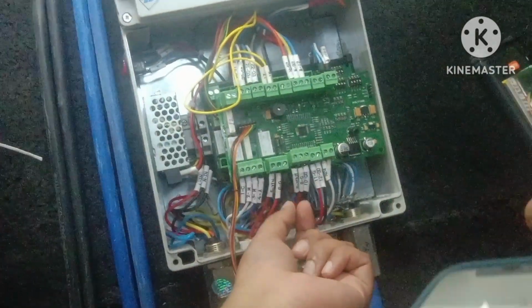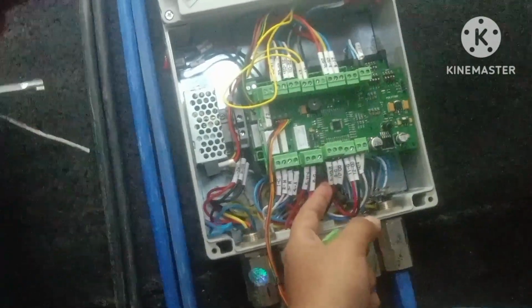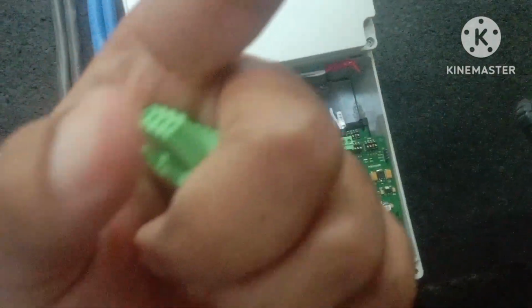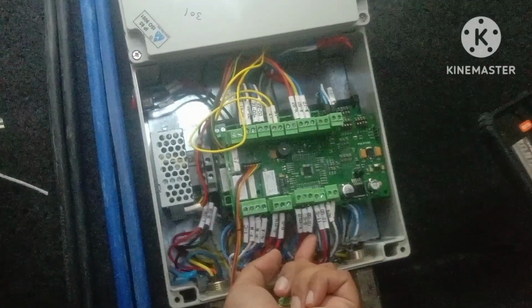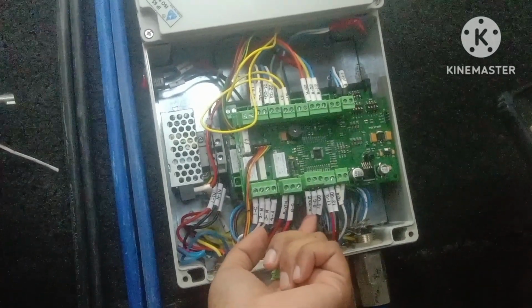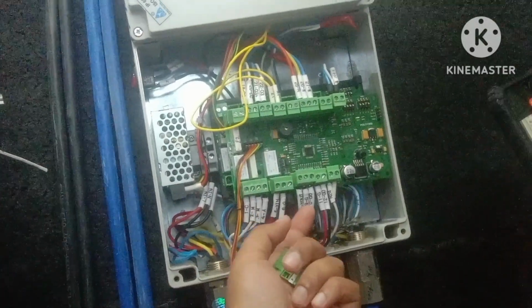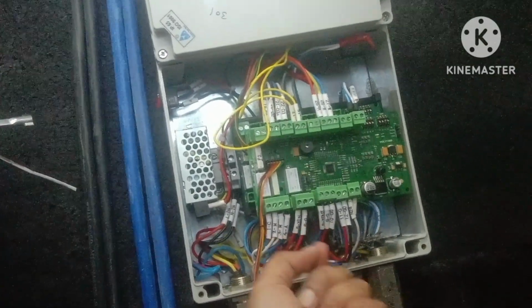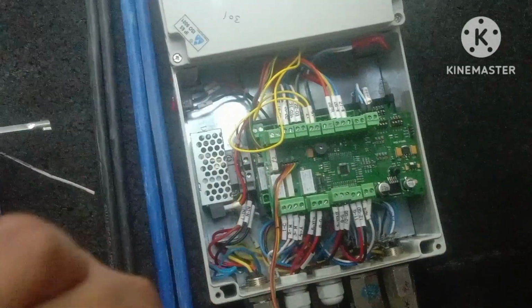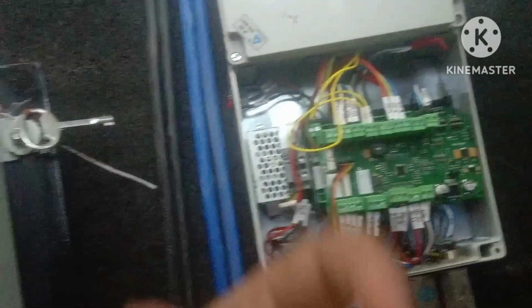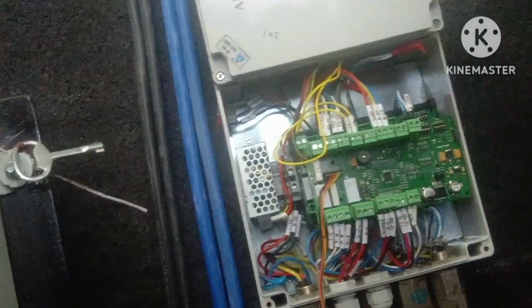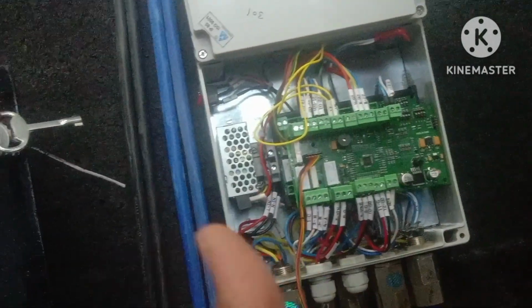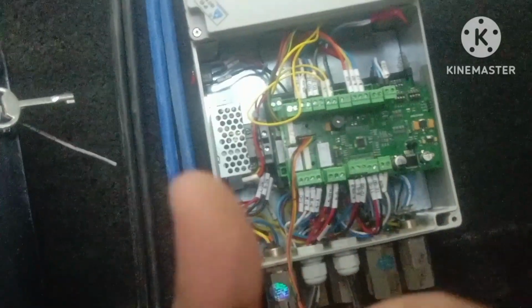Then this is going to the valve supply, the actuator valve supply. If we are not getting the feedback, it means there are some issues. The set temperature versus actual temperature, so it should have opened the valve, but somehow the valve is not opening. Maybe the actuator is not opening. We can troubleshoot that from here.